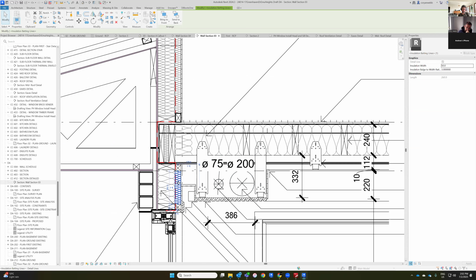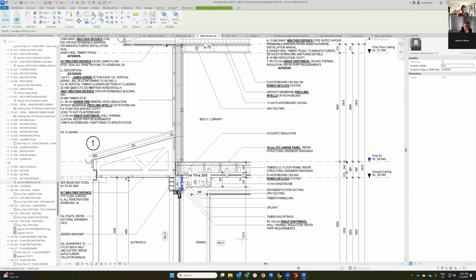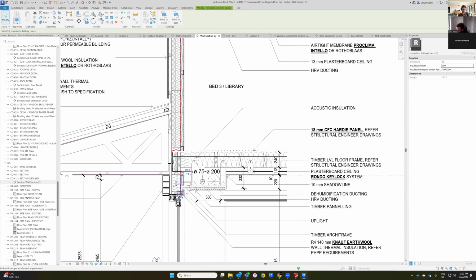And you're saying, Mark, we don't need this insulation? No, I haven't calculated with that. Okay. Save some money. Yeah. This is all coming to light because I'm designing a high voltage system for a huge data center at the moment, and we're having an absolute fight trying to fit how many high voltage cables in conduits they want and maintain separation of them so that they don't derate by stupid amounts.